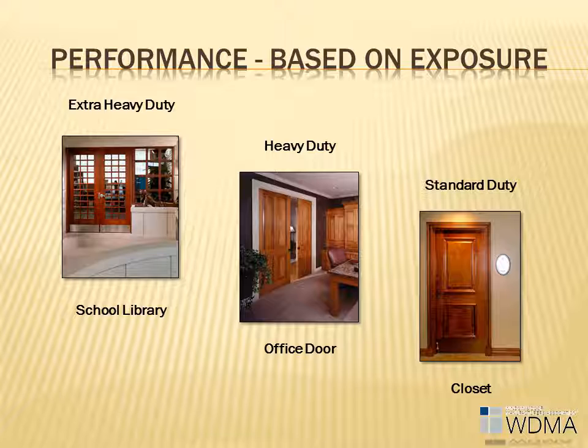To correctly plan, design, and select interior architectural doors, specifiers need the proper tools. They need to know which door is correct for the opening based on code, and which door is right for the type of environment in which the door will operate. A door in a facility that experiences heavy use on a daily basis must be able to perform at a higher level than a door that has little or infrequent use. That's the real world, and that's how doors must be manufactured and specified as well. That is what ANSI WDMA I.S.6A 2013 does.